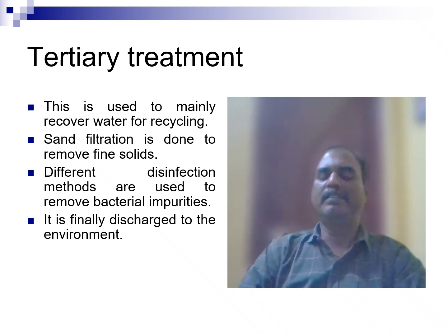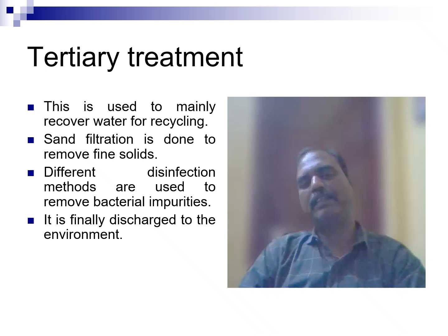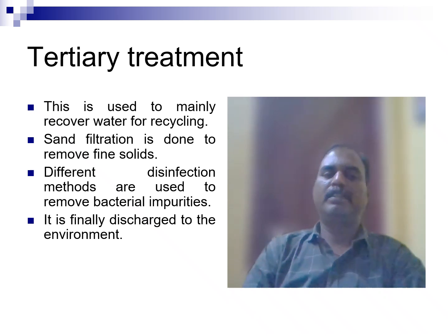According to the quantity of water, they calculate the bleaching powder. Then it kills the microorganisms present in the wastewater. After checking the pathological impurities as well as microbes or pollutant level, the water may be discharged into other water bodies.